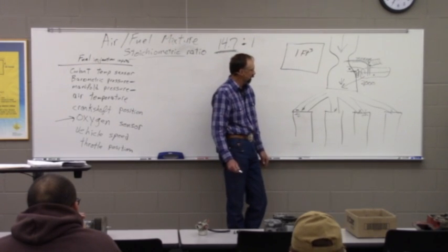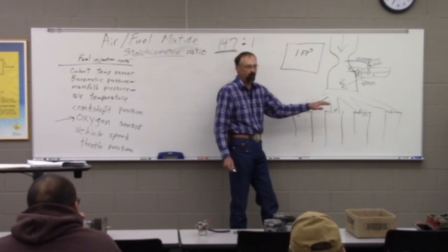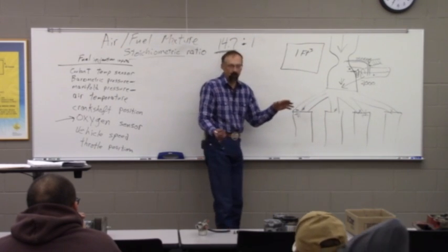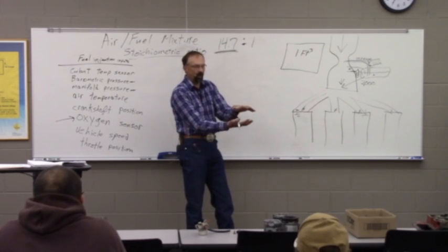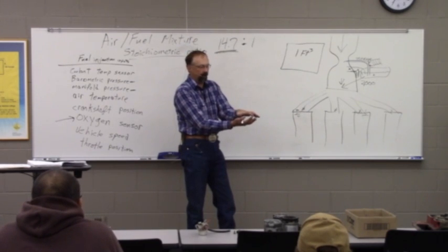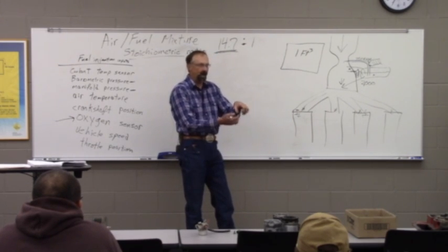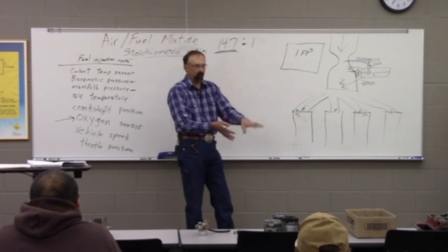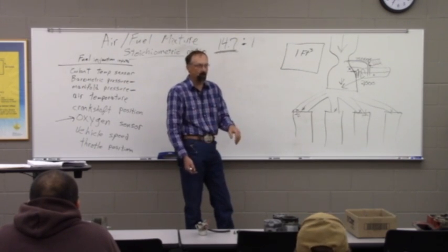Interestingly enough, that is more or less what's always had to happen in a diesel engine. Because if you remember what we were talking about earlier, in diesel engines we're compressing all that and getting our temperature high. And then when we're ready to fire it, we're squirting the fuel injector. And as the fuel comes out of it and vaporizes from liquid into a vapor, it burns. So we had to inject the fuel right when we wanted the combustion.